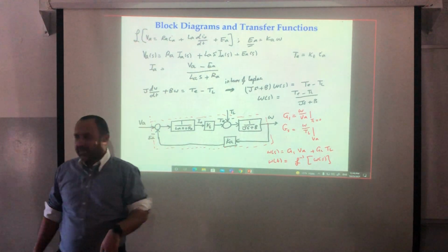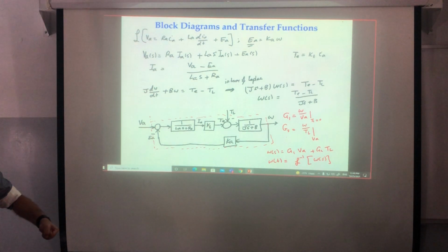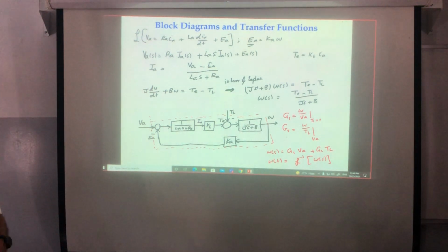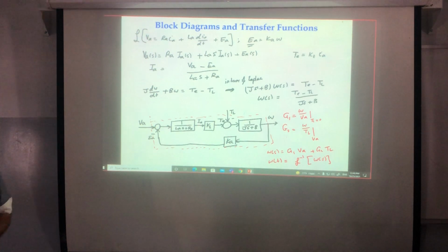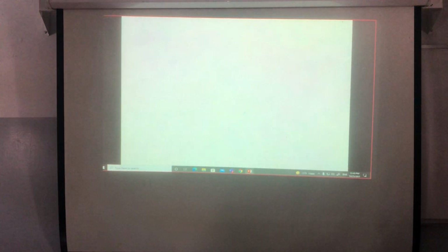Imagine that I'm doing a block rotor, which means that I'm imposing a small DC step, otherwise my hand will be out. Then I'm capturing the current response. What information can I get? Time constant.